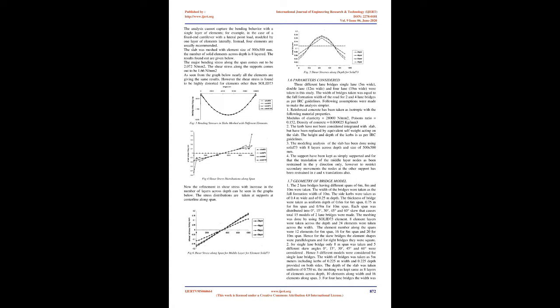1.5 Validation of results and selection of element type. For the modeling of slab bridge following elements were taken and the results were verified with conventional analysis. This was done to select one particular element which is most suited for study. The test problem taken is a 15 m wide slab of span 10 meters simply supported at both the ends. The material is taken as isotropic concrete with following properties. E, Modulus of elasticity, equals 28,000 N/mm2, M30 grade concrete.